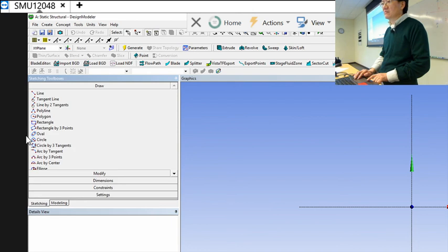And you click the sketching tab below the toolbox. Now you will see Draw, Modify, Dimension. Click Draw to expand the sketching features available. Once you have that, you see the polygon. The default has 6 sides. Change that to 3.